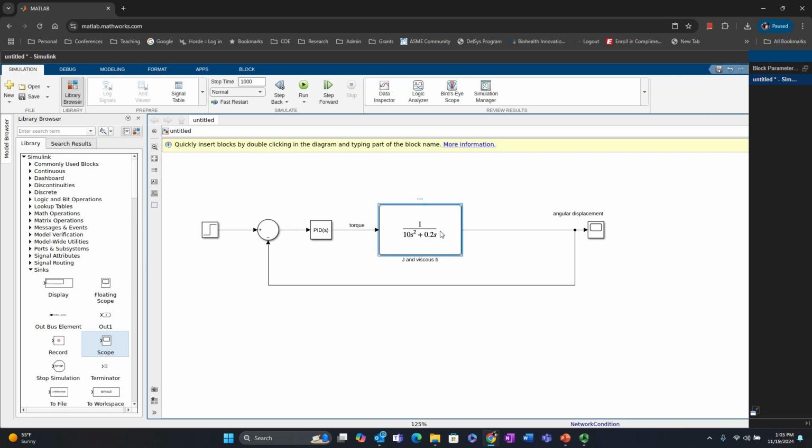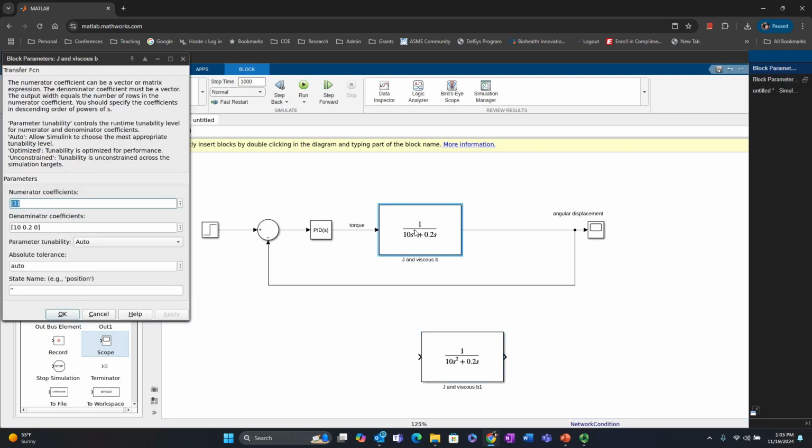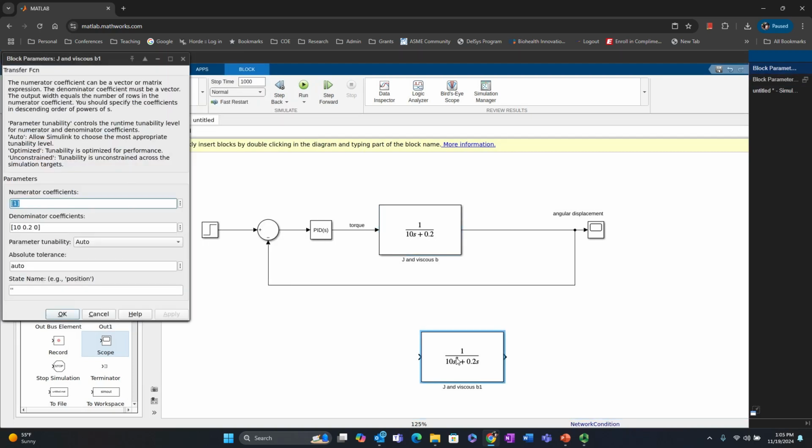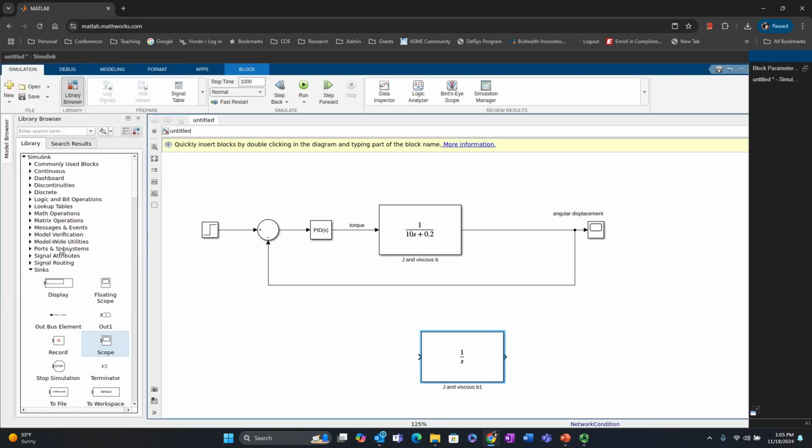What I would like to do, however, is to split this into two parts. I want to remove the 1 over s factor from the first block. So I will write it like that, and then I'm going to make this a 1 over s. Okay. Effectively, it's the same transfer function. When they're multiplied back to back, we have the same effect, right? But by doing so, I split them. Their multiplication remains the same as it was before when they were combined together, right?